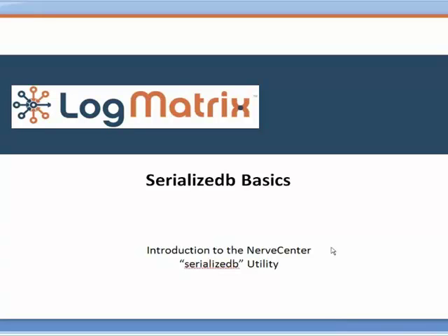If you are on 5.1.03, that is major version 5, minor version 1, patch release 03. Going from 4.1 to 5.1, you should serialize the database out. It creates a particular type of file that is then used to serialize into the next version. It creates an ASC file.